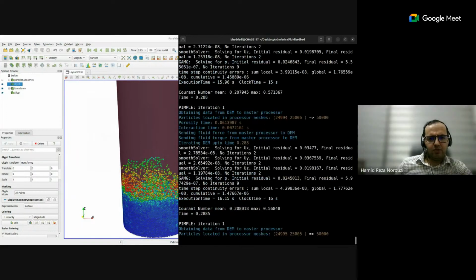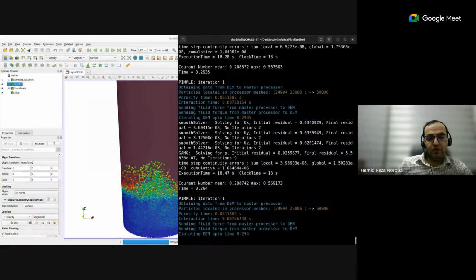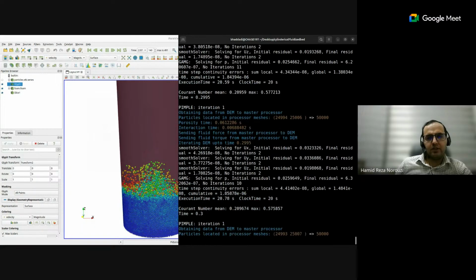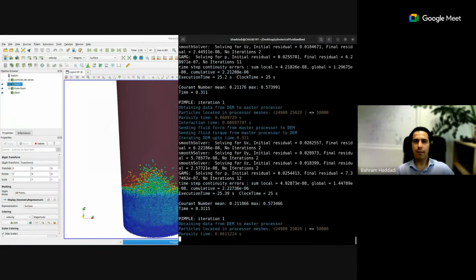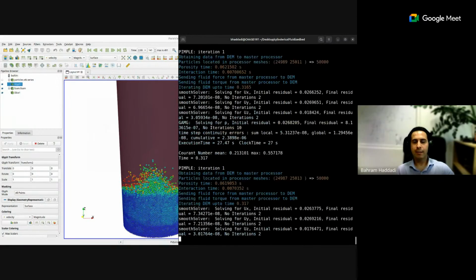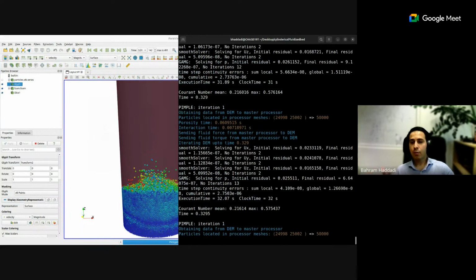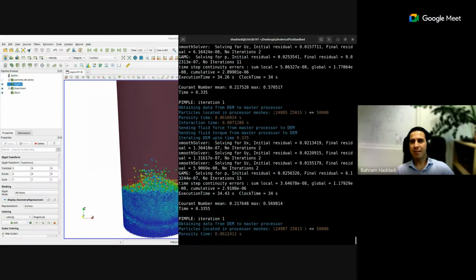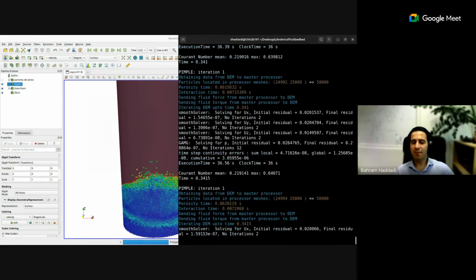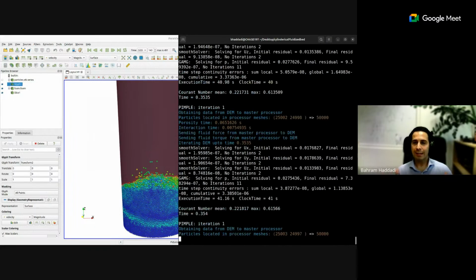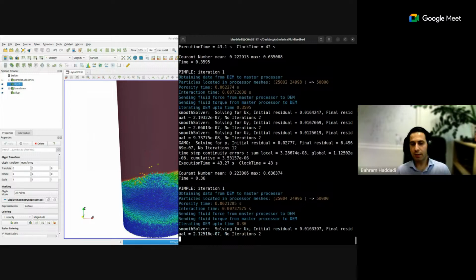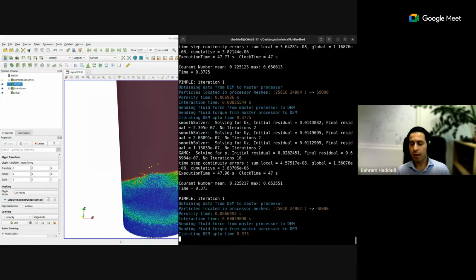Yeah, and what do you recommend, when do we have to use parallelization on the CFD side? Do you have any recommendation? Basically, yes. Thank you. That's a very good question. Basically, we can follow the same trend as we do on the CFD. So whenever we have more than 50 or 100,000 cells, we should go for parallelization for a simple typical CFD case. If you have reactions or some specific things in there, then that's a different story.